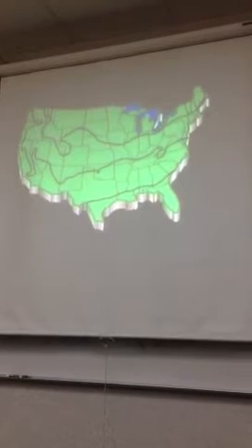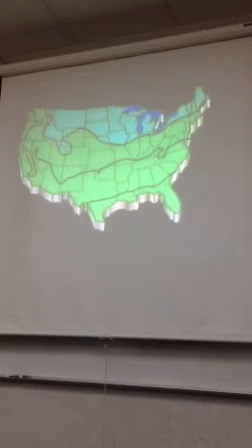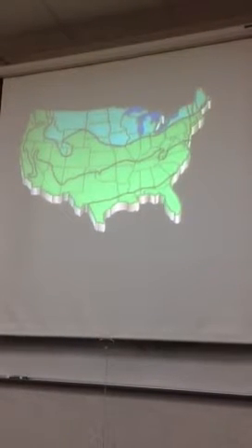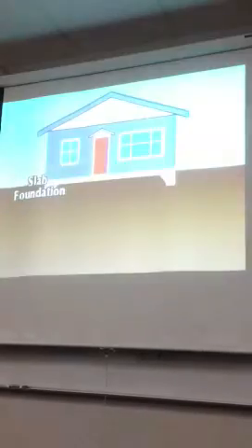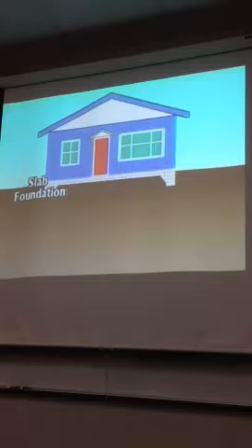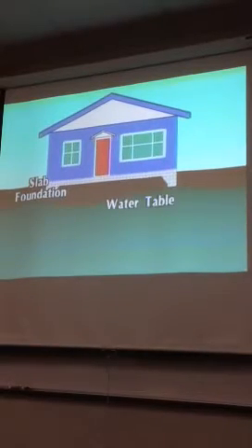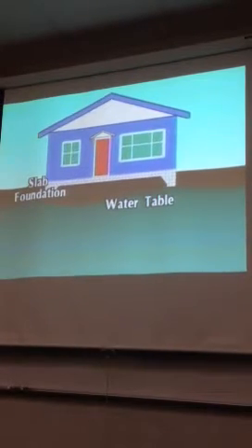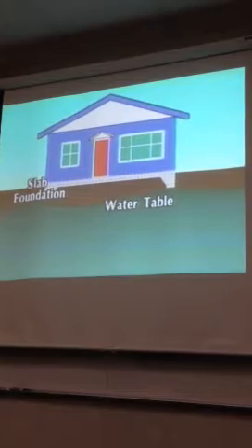One type of slab foundation is called a floating slab because it sits directly on top of the earth. Because of this, floating slabs aren't often used in certain areas of the country where the ground freezes in winter. You see, when soil freezes and thaws, it shifts and moves. So a slab foundation built on this type of ground would simply move along with it. What about bigger buildings?